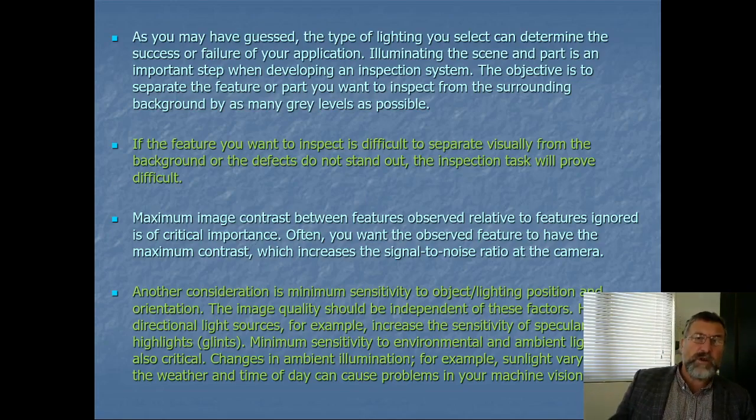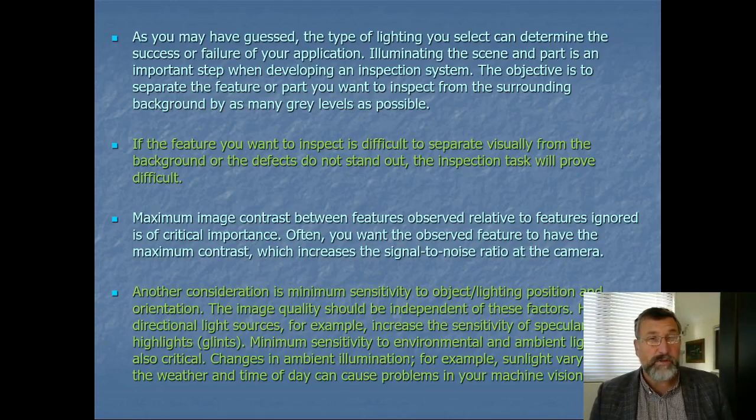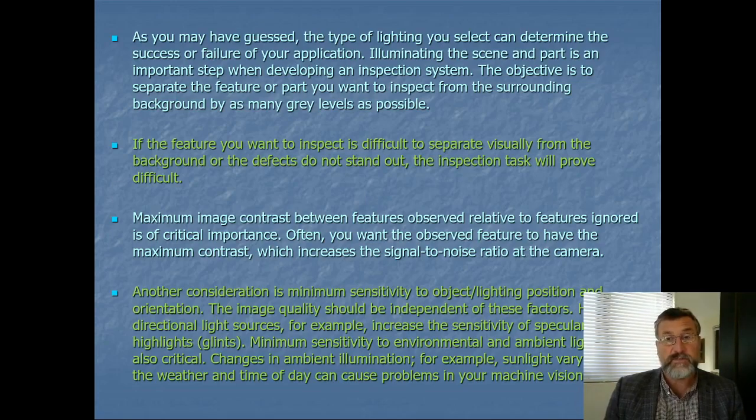One thing you can do, I mention this because one thing you can do to improve the signal to noise ratio, is to use a laser of a particular wavelength and then match that to the transmission characteristics of a filter. We buy lots of filters off various companies. And then the signal to noise ratio will be increased dramatically because a lot of the background radiation from various object lights in the lab or wherever will be blacked out because we're only looking for the wavelength that the laser is at. So that's a technique definitely worth doing if you're using a laser.